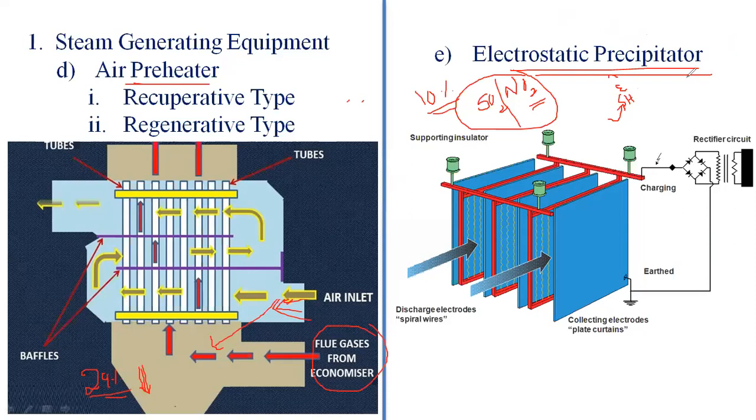With the help of the electrostatic precipitator, the primary collector, and a supplementary unit, the cyclone collector. Whenever the flue gases enter the duct, an additional charging DC supply is given. Due to that, the fine particles are absorbed and discharged to the bottom of the furnace. Even so, 1 to 2% will still enter the atmospheric air.